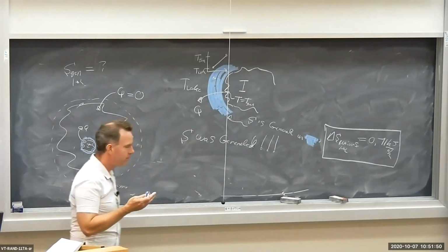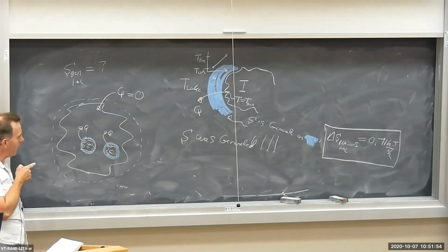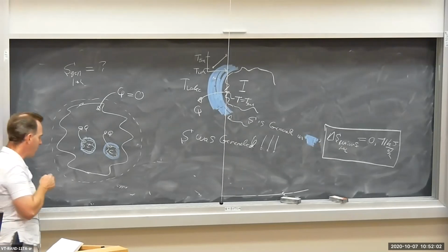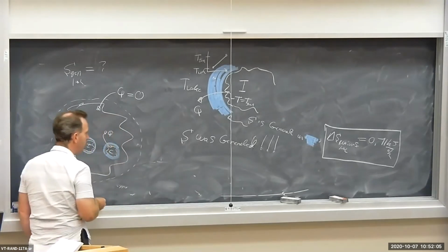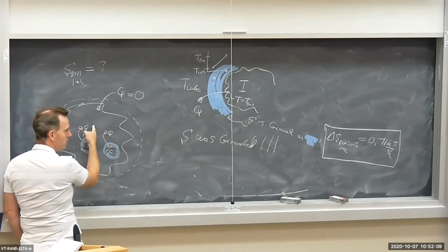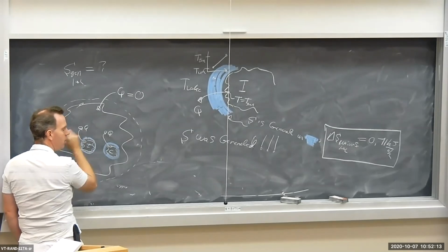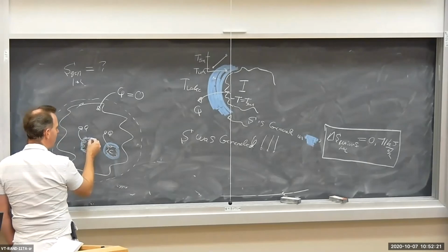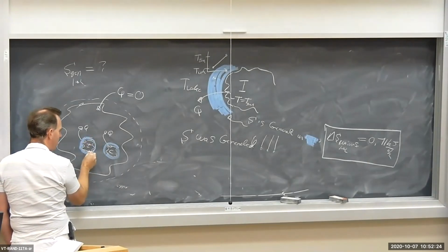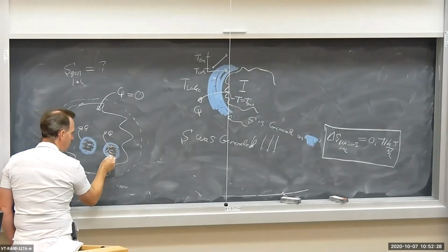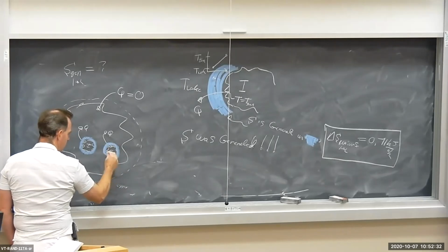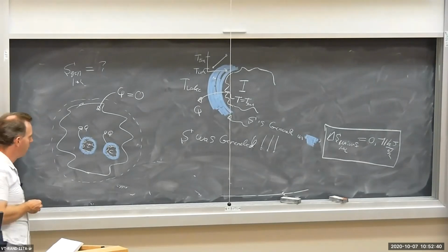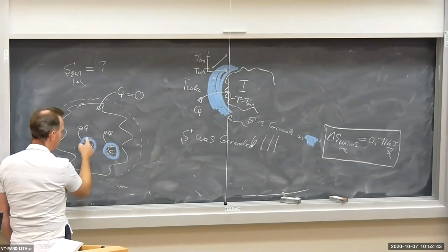Okay, so let's recap this. This is an irreversible process. Heat is being transferred from two hot materials into a cool lake. We're going to get entropy generation. Where is the entropy being generated geographically? What's the source of the entropy generation? It's not in the lake water, because we've defined the lake water system such that the interaction temperature is the lake temperature. It's occurring in a transition region near the iron, in which heat is being transferred from the hot iron and copper into the cool lake water. So entropy is being generated in this buffer or transition region.